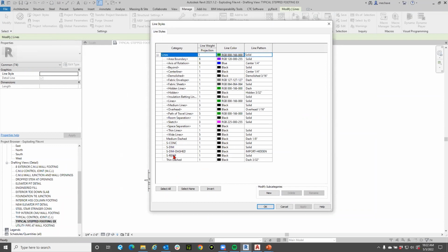And it doesn't only just bring these in. If you have dimension styles or hatch patterns, it'll bring them in and add them all. They'll be baked into your project now. And that is unnecessary content in our project that we don't need moving forward, right? And if we have more content in our project, more processing power we're going to need for our project moving forward, which just tends to have lower speeds in what we're going through and practicing, right?